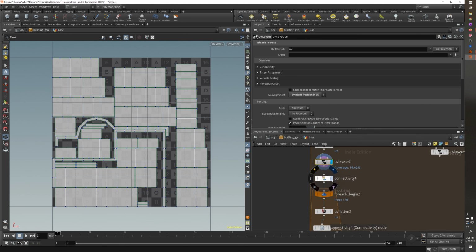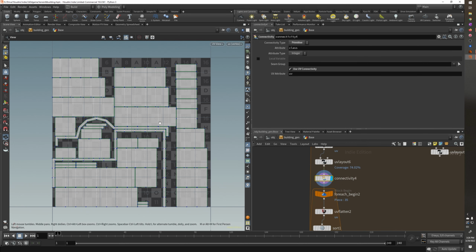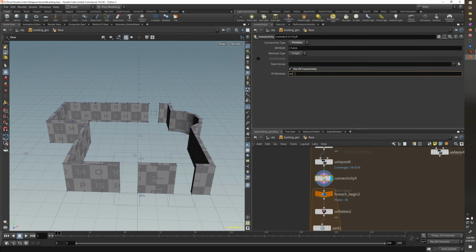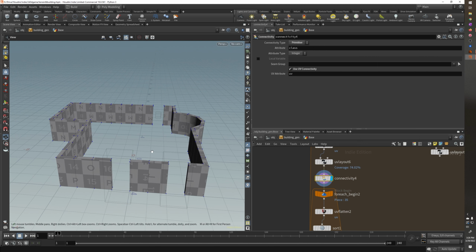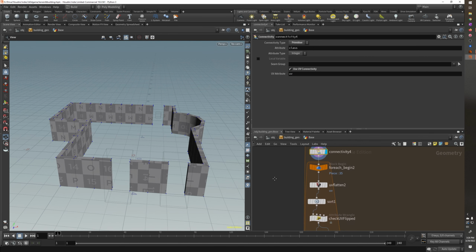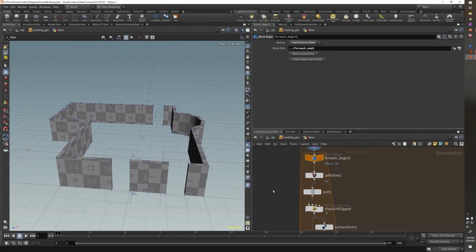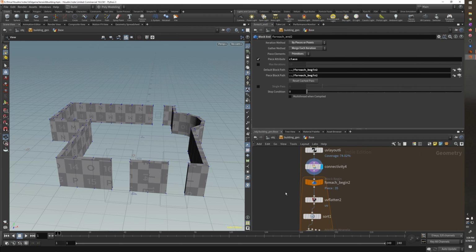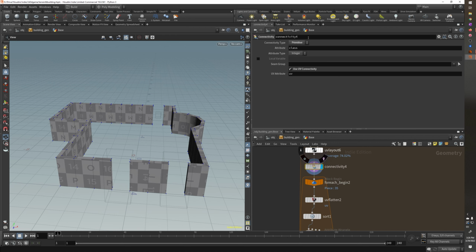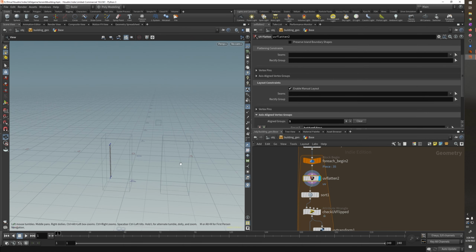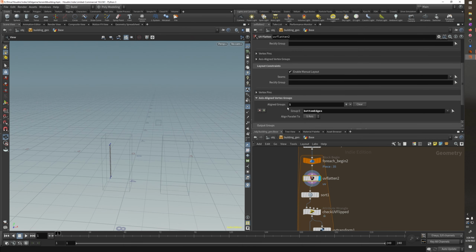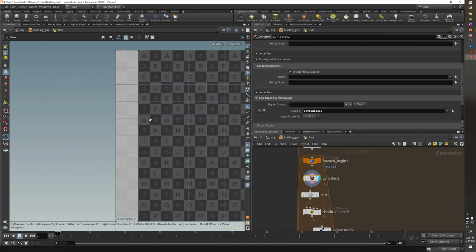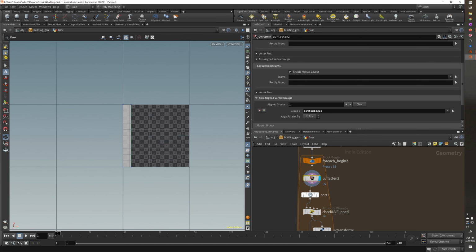And then we get a connectivity, and the connectivity node is, you can add a UV connectivity, so it loops over every single UV shell instead, which is really nice. So then we go through a for each over a class attribute, similar to how you would do like a for each object, for each connected piece, but instead of using primitives, we're using the UVs. Excuse me. And then we do another flatten node. And then this time we do use the bottom edges. So we're basically like re-flattening out the UVs.